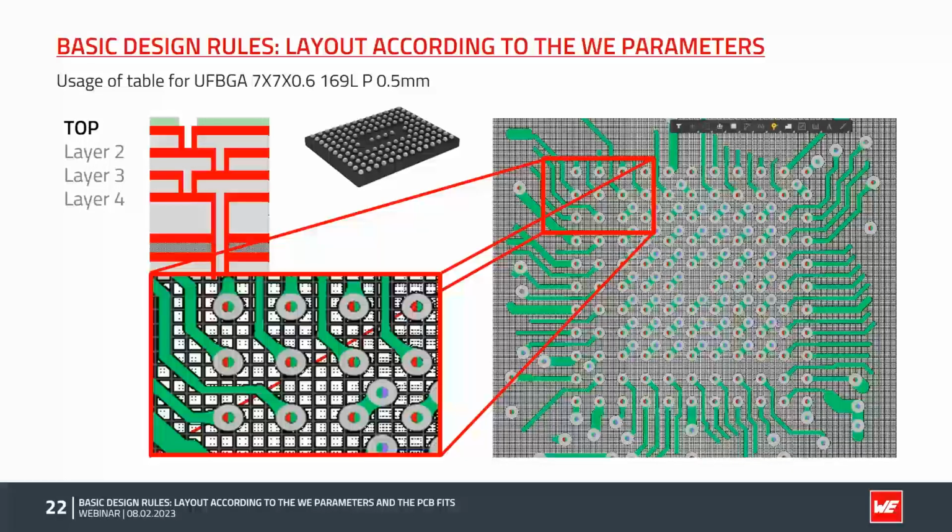But in this case, the design uses 70 micron line and 90 micron separation or clearance. So this also enables us to cover the line with solder mask without issues, and gives us more yield in the production. More separation, more copper spacing makes the production much easier. So that's how we can read the basic design rules and apply them.